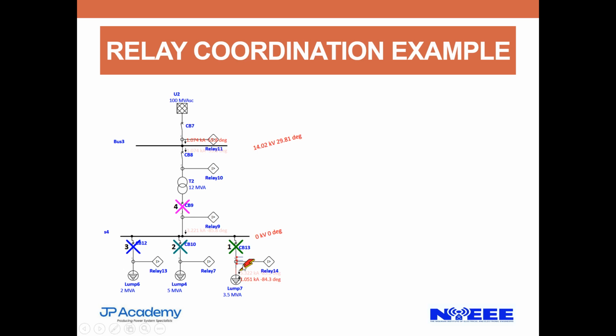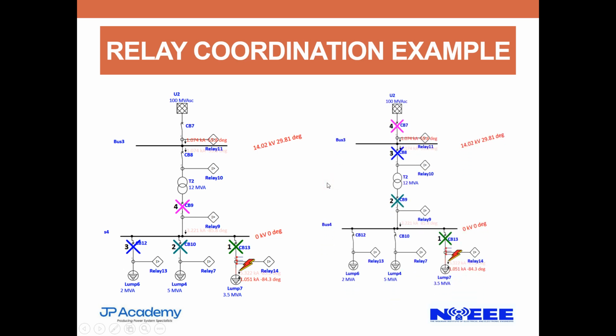Remember, there is a fault here, so it knocked off all these feeders before isolating the main feeder to the bus bar. So I would like to hear your thoughts. Is this properly coordinated? Should this be the right sequence? Or, no? Okay, we'll have another example.